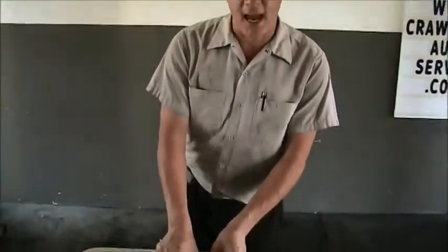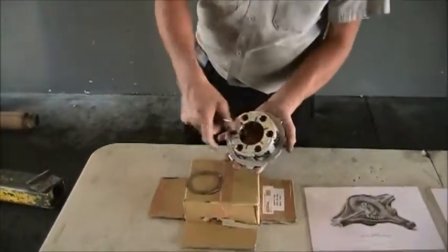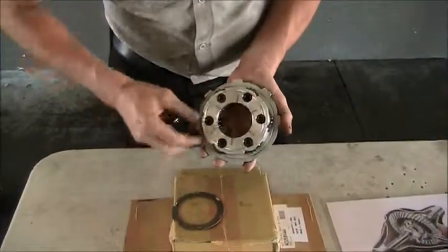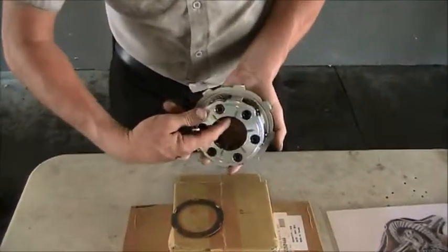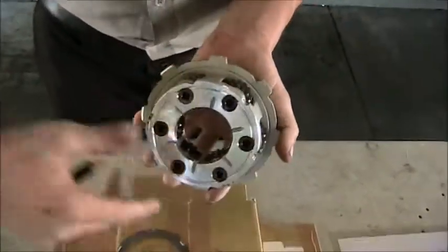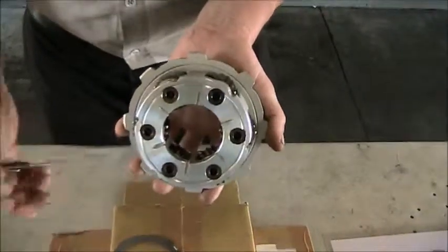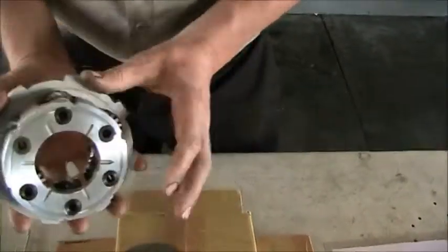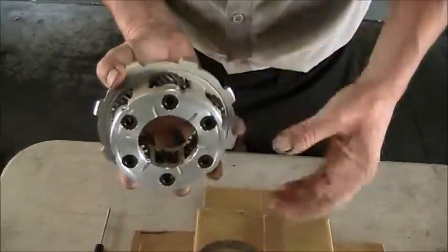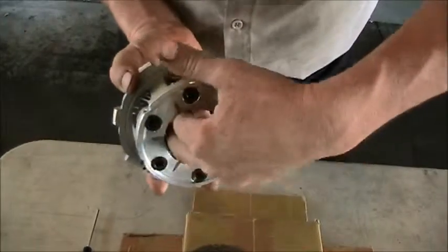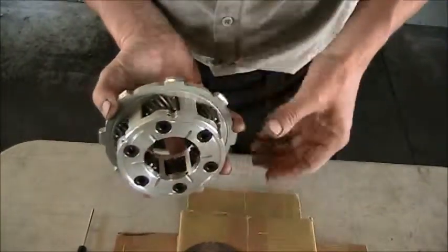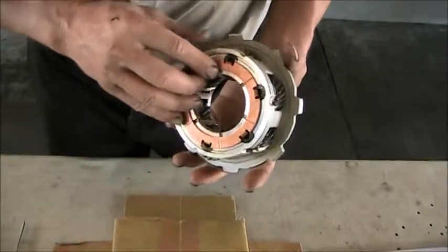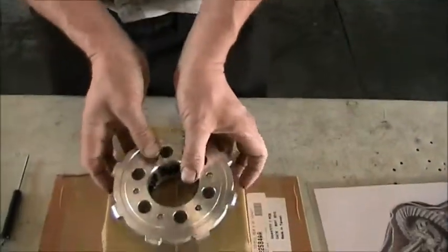Now, this is an actual planetary gear set. We don't have the sun gear, which would be the gear inside of here that turns all of these. So as these turn, then they would turn the planetary gear, so you get a gear reduction. But as I said, you can hold this part of the transmission, you can hold the sun gear, the planet gears, or the ring gear independently, all of which will give you different rotations and different gear ratios.